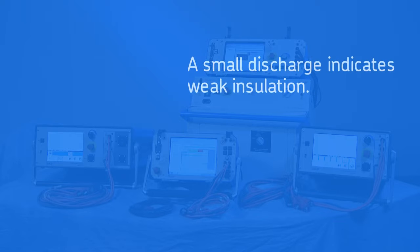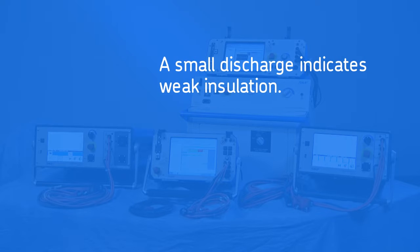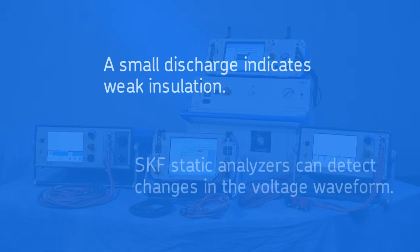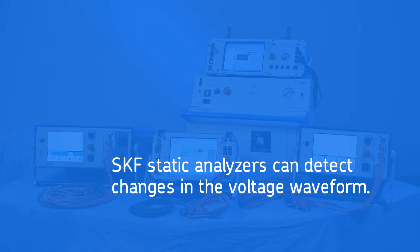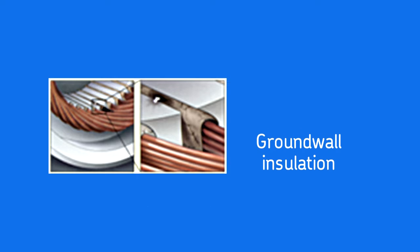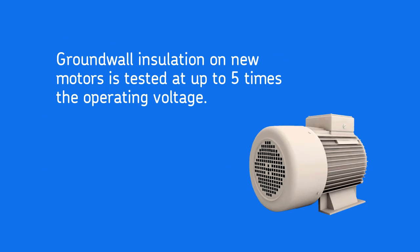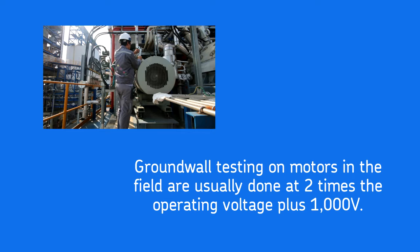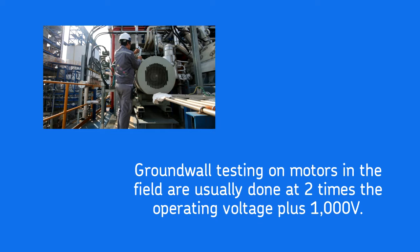If the winding insulation is weak, a small discharge will occur, which causes the voltage waveform of the winding to change. SKF static analyzers detect and report this change. The ground wall insulation is the insulation between the stator windings and the stator core. When the motor is new, this ground wall insulation is tested at voltages up to 5 times the operating voltage. For motors in the field, ground wall testing is usually done at 2 times operating voltage plus 1000 volts.